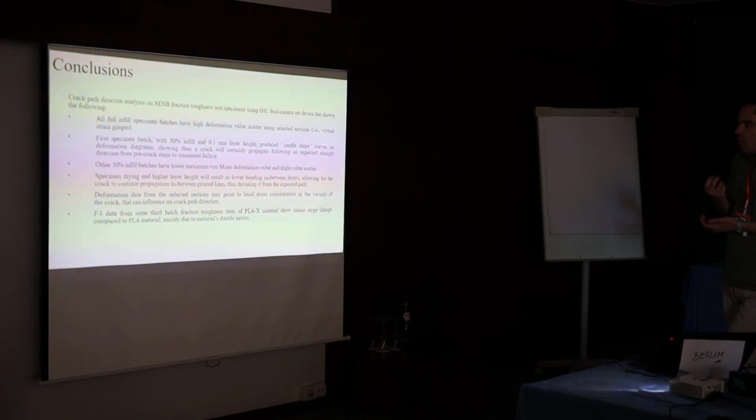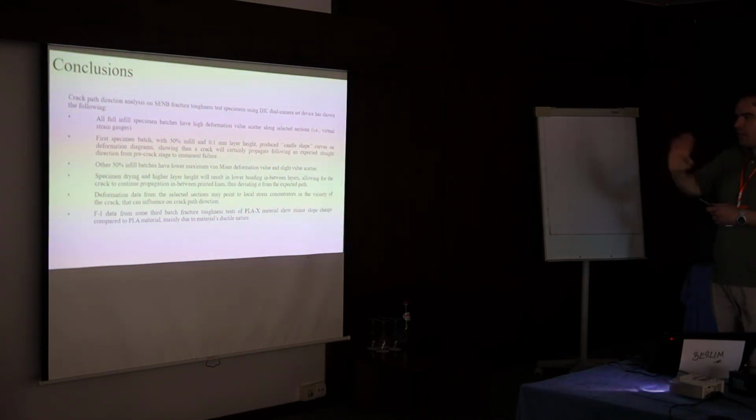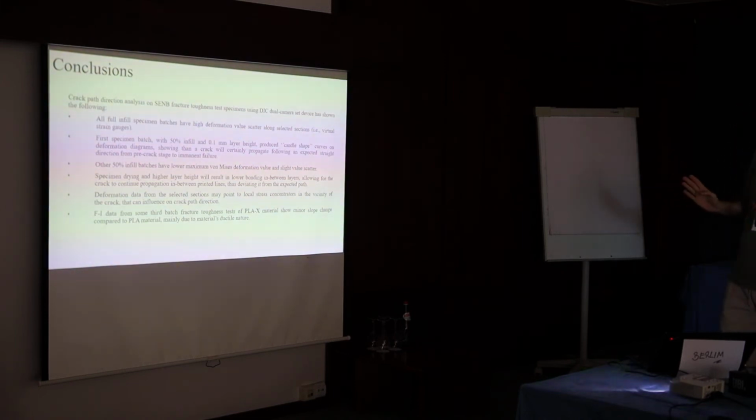We've seen that most probably the straight crack propagation path will be in the specimens with lower infill percentage and higher layer height, producing on the diagram these candle-shaped curves. So in the middle part where we expect the crack to propagate, we'll have the highest deformations, and on the sides we won't have almost any.